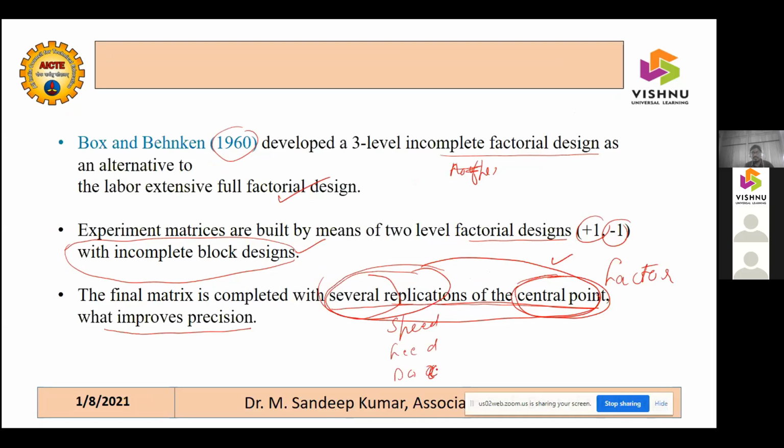I'll take this for this example. It was 90, 120, 150 velocity, meters per minute. Feed was 0.1, 0.2, 0.3. So I had already done experimentation, from previous studies or from initial trial or pilot experiments. I know that this combination is giving the right results for me.